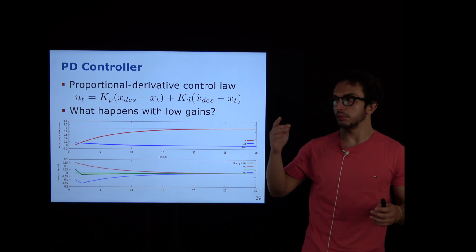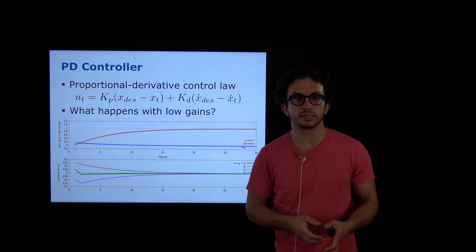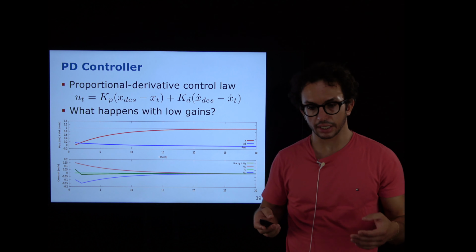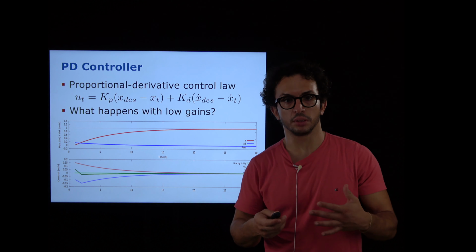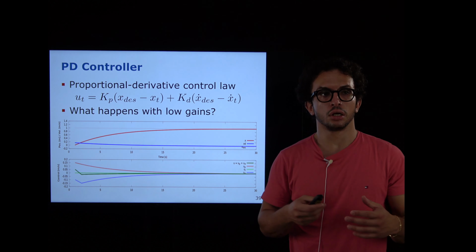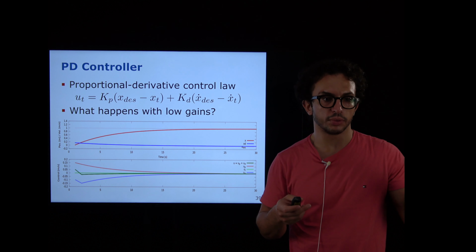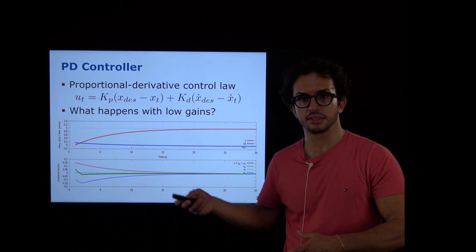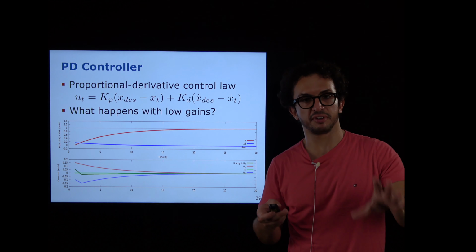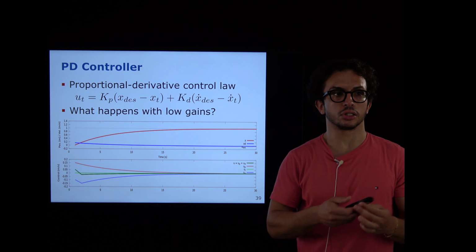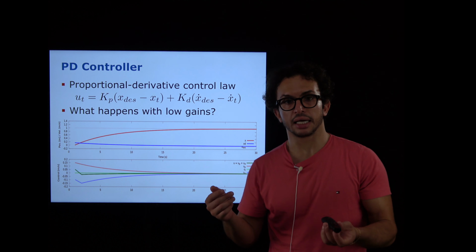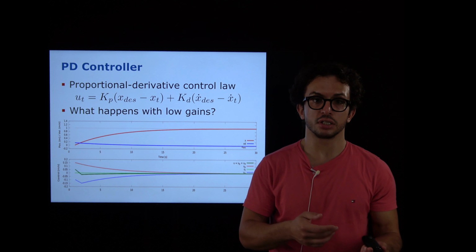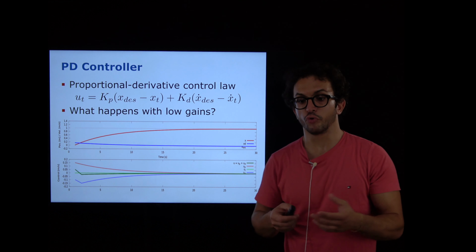And the thing with gains is always, this is also why there are heuristics for tuning the PID parameters, and one does not follow exactly whatever is written in the Ziegler-Nichols table, or just fix the parameters once and for all, that there's always a trade-off between speed and overshoot.